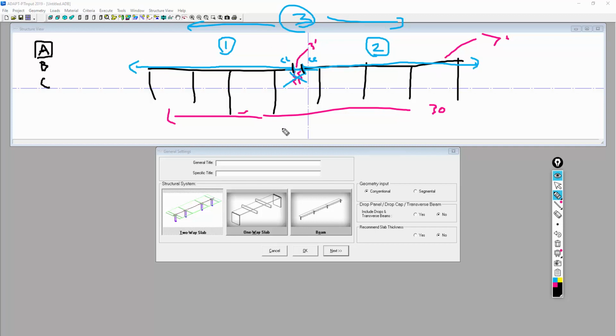So in this program, which is primarily built for post-tension structures, tendon A goes from this end all the way to this end. It could be a dead-live, it could be live-live, or live-dead in terms of the anchorage. And here I'm just drawing these flat. In reality, they're going to have some sort of shape to them. So because tendon A passes through this pour strip, we can't really use it. So we're going to actually set that to 0.